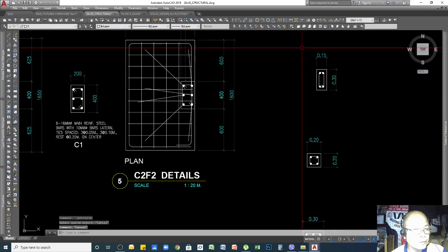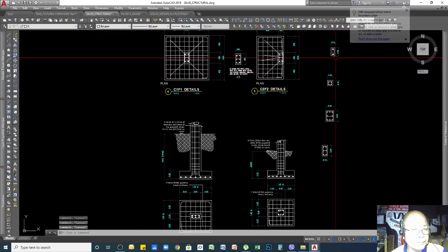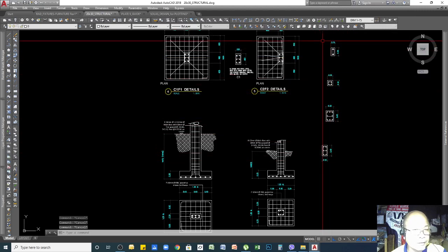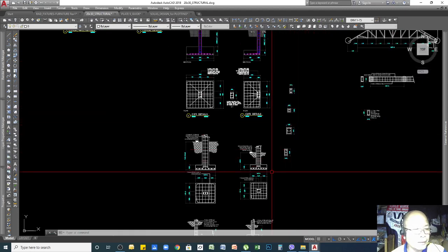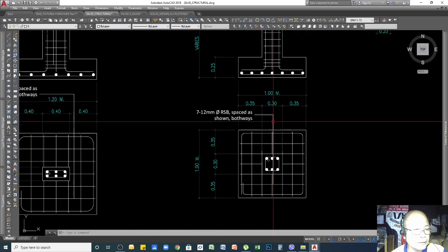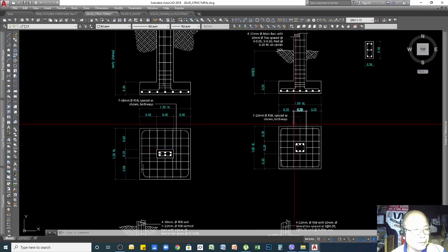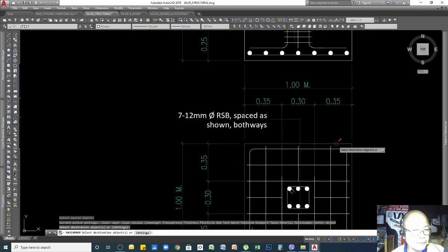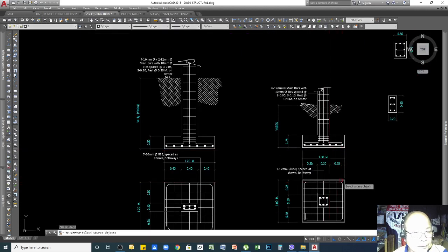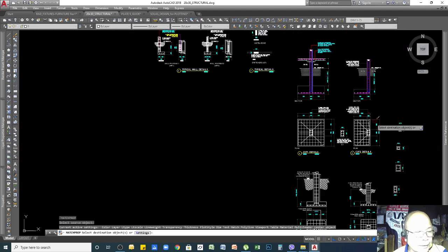By the way, these columns, you can adapt by putting them inside whatever the size of your footing is. I indicated here different sizes of columns as well as rebars. For example, you will adapt this footing of 1 meter by 1 meter. Since you have a one-story floor plan, 1 meter by 1 meter is enough. I will make this a complete guide for you. All right. Top, then for your main bar.